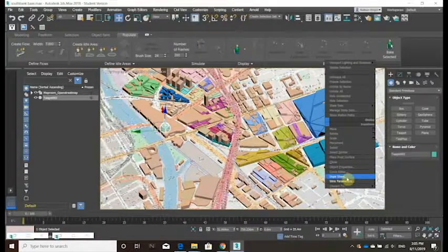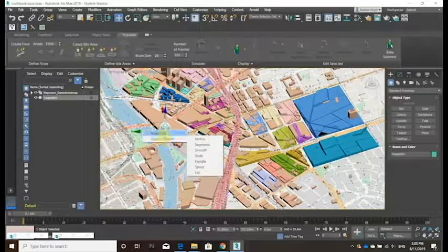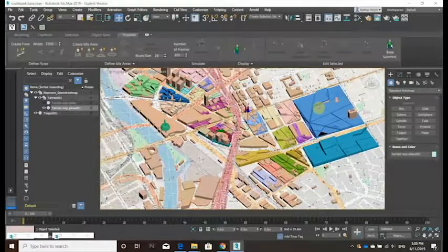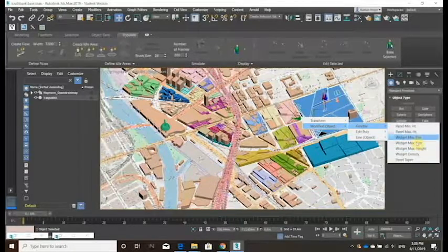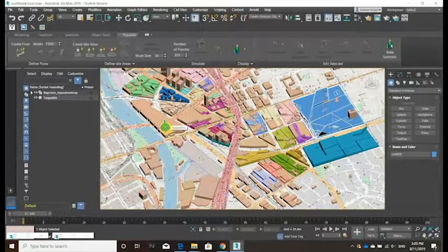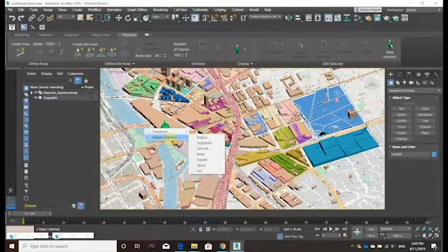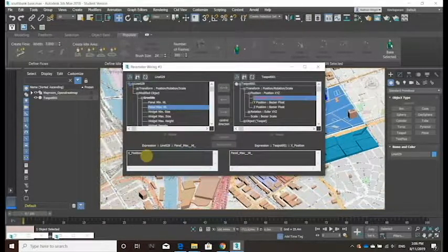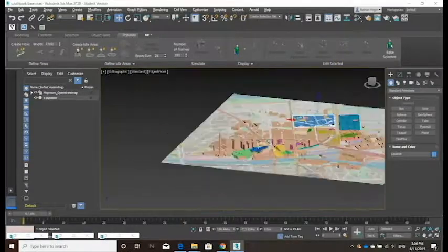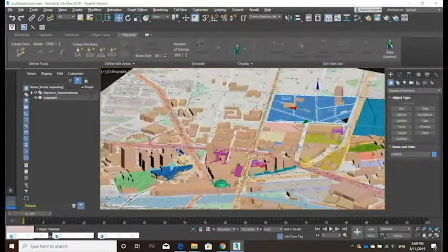So I'm going to right click on this one, wire parameters, click on the greeble, wire parameters, transform, modified object greeble, max panel height, and then also the teapot, and transform position, X position, and then we'll go divided by, let's go 8, both way connection, connect.